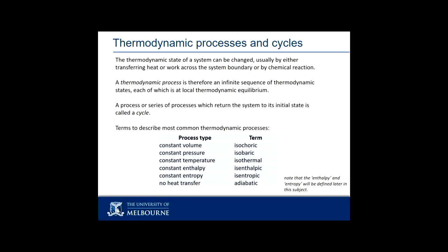And then enthalpy and entropy. Enthalpy is a form of energy, entropy is a form of disorder. You can have isenthalpic and isentropic processes. All of these are straight lines provided that the property is on the axis. When the property is not on the axis, you need to know the maths of how that property connects with others. If I had a constant temperature process, but I was on a pressure volume graph, it wouldn't be a straight line, and I would need some information about how pressure and temperature change for me to plot it. Luckily, we'll do that in about 5 minutes.